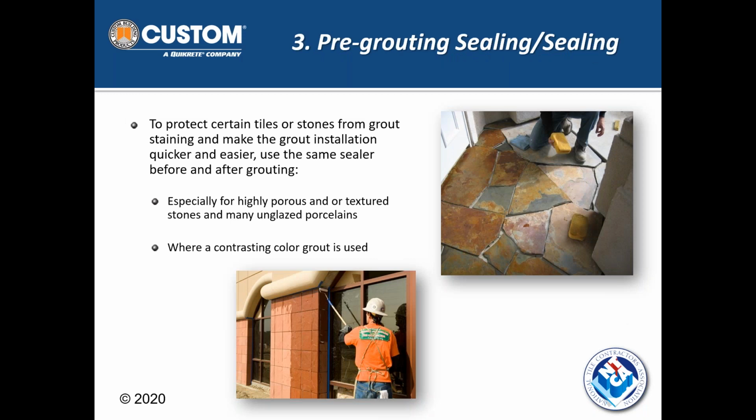So let's get to number 3, pre-grouting, sealing the stone. Pre-grouting sealing just simply means you want to take the same sealer that's going to be used on the stone or the tile after grouting, and use that same sealer before grouting. That's what we call pre-grouting sealing or pre-sealer.